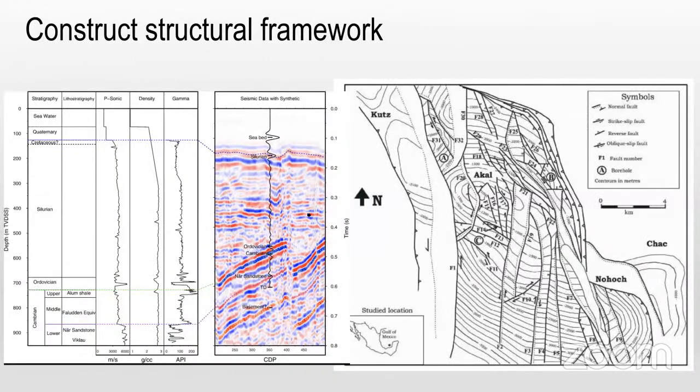Okay, right now you create a stratigraphic framework of the reservoir. It means that you create horizons with zones and subzones, and after that you must import the faults. You must import the fault lines and displacement. You can import the faults or displacement of the faults in 2 ways.